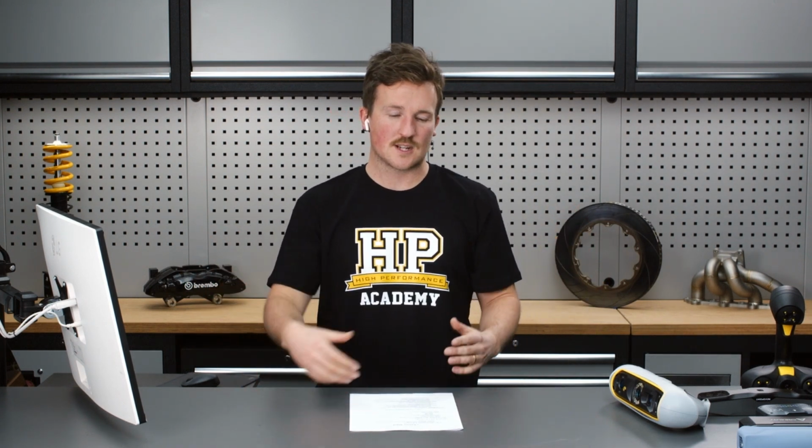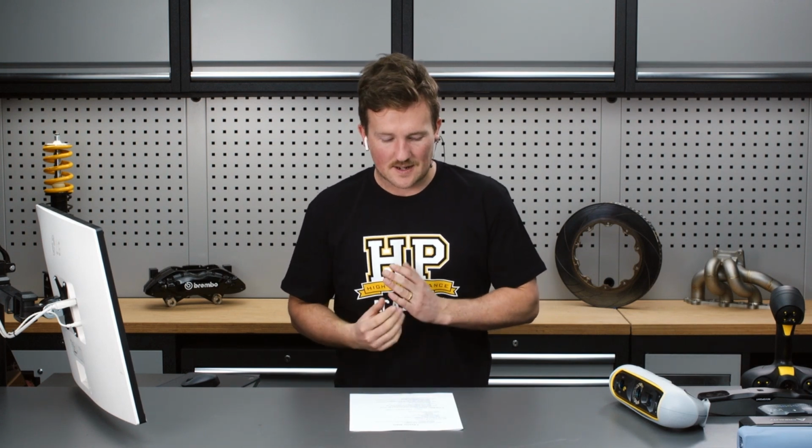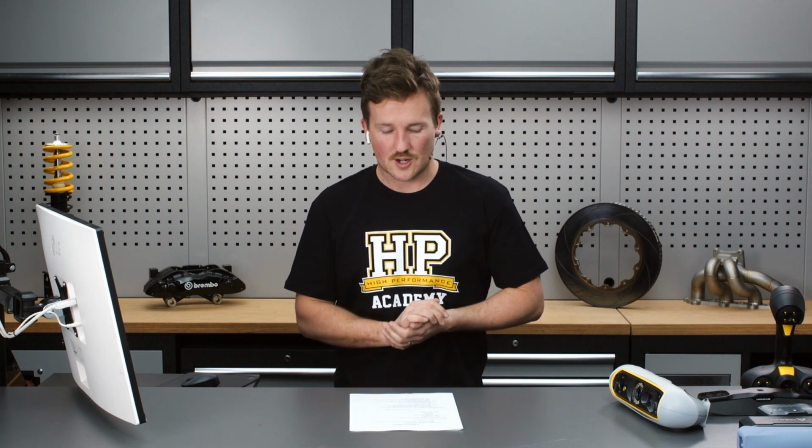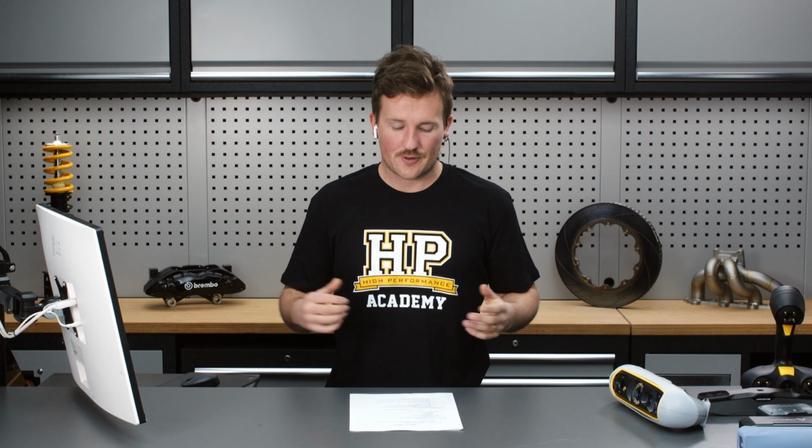Now, that's not always the case, because if we're scanning something small on the bench in front of us, say on a turntable, we might not want to capture such a massive area if it's just a small target, because we're just going to take in a lot of the background that we need to remove afterwards anyway, and that's just going to slow down the processing and things like that as well. So a lot of these really depend on the application or what you're going to be scanning. Of course, if we're going to be scanning something like the exterior of a vehicle, then having a large working distance and a large field of view or capture area is going to be a beneficial thing.